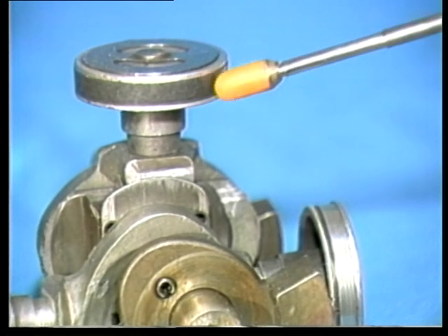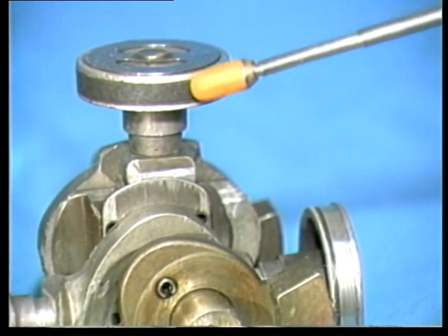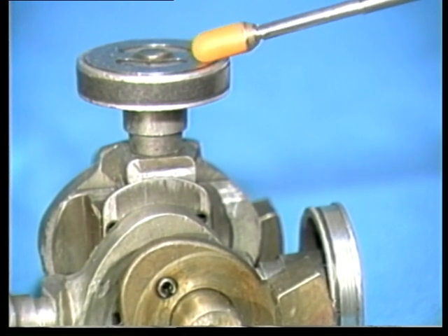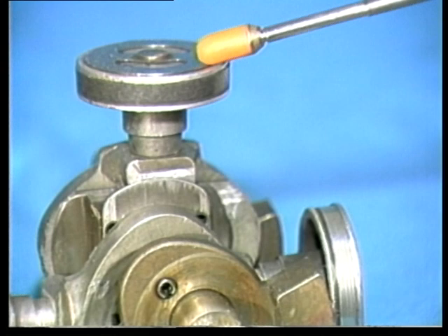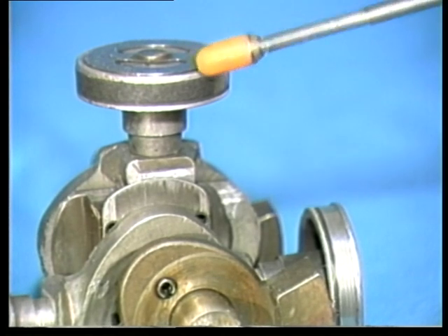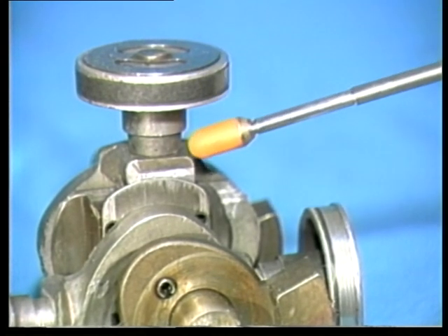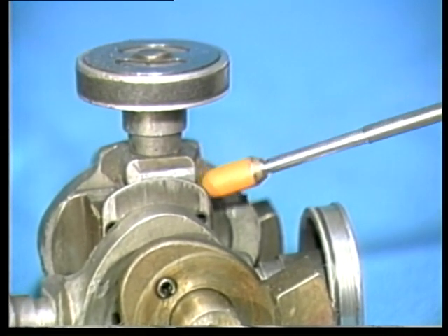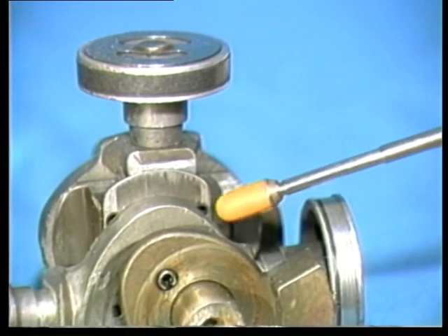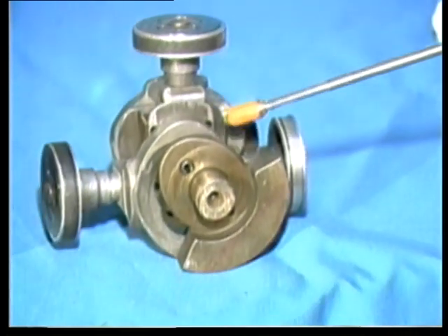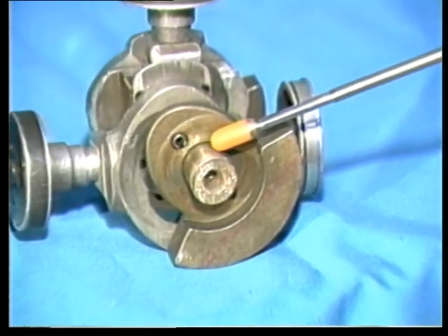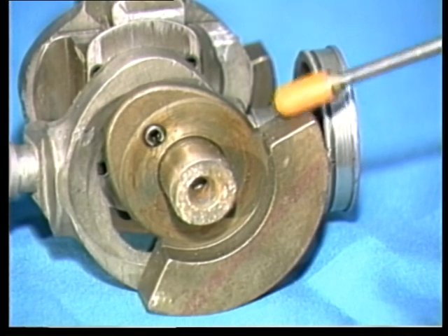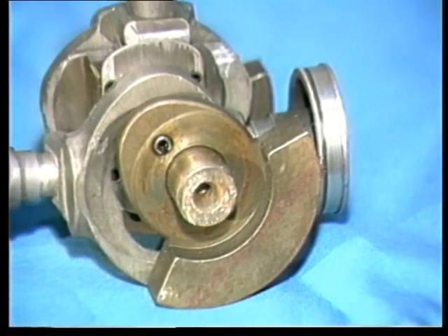This is a crankshaft piston assembly out of a 4-cylinder radial compressor. Note that its construction is quite different. The piston houses a suction reed valve, and a conventional connecting rod is not used. 4 pistons are mounted on 2 yokes. The yokes react to motion from a slider block that rides on the crankshaft eccentric. As the crankshaft turns, the eccentric acts on the slider blocks and yokes.